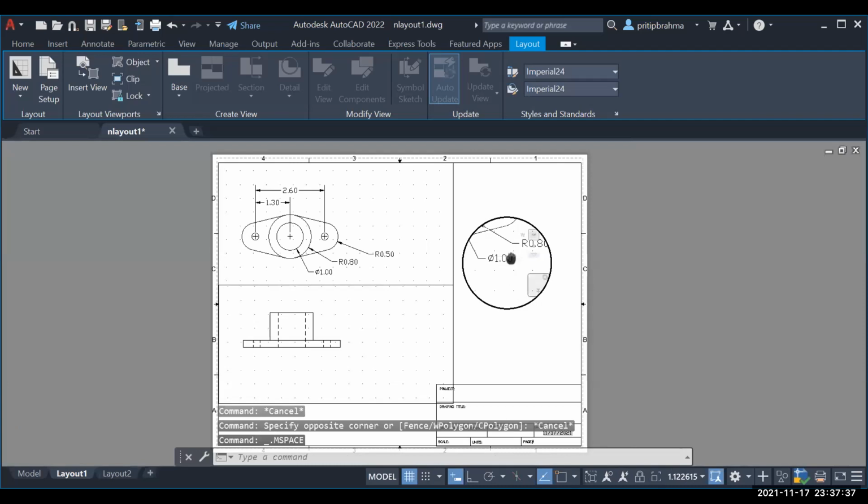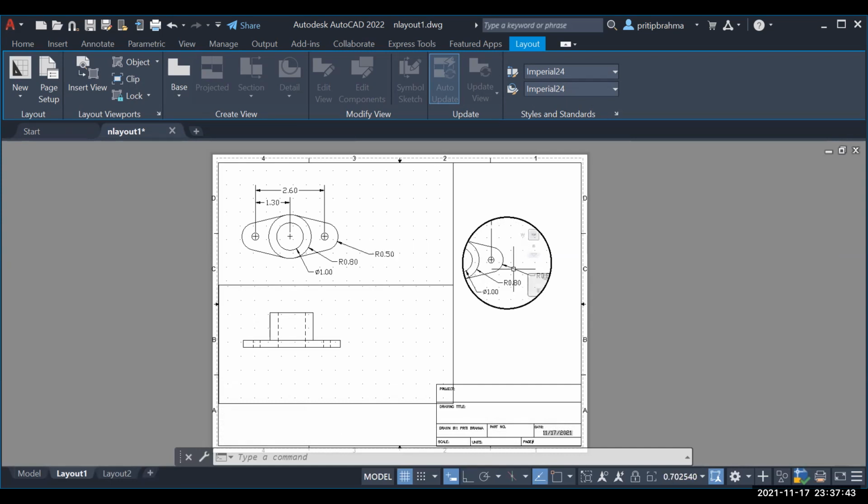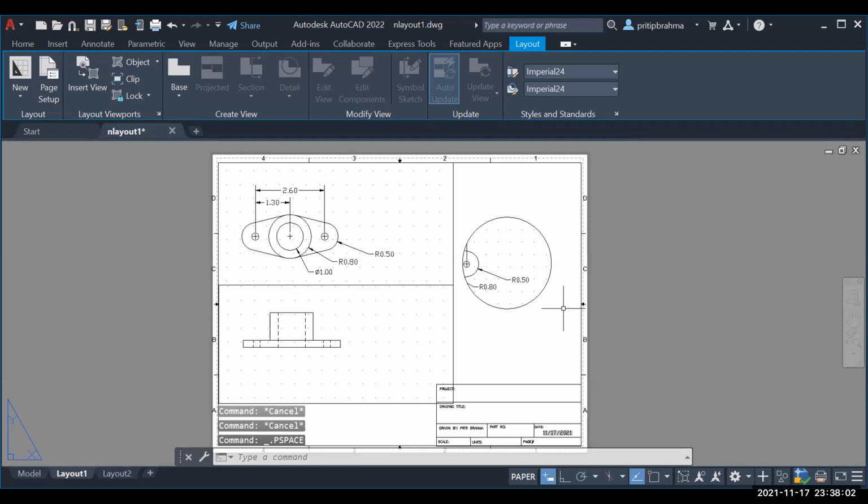And then I just wanted to show some tiny piece of this. Let's see. Just perhaps that edge, right? In my circular window, it's like a zoom in window, right? On a drawing. So you could do something like that where you create a circle. In this case, in your circle, you may actually want that edge to show of your viewport because it's a circle like that. So you can create different shapes of viewports. You can create different configurations of viewports. I showed you how to do 4 of them.